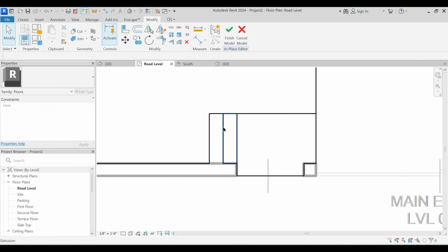1 to 2. Uh-oh, sorry. One step. Actual tread depth here, this is 10 inch. So see, only 10 inch. So 10 inch, and the flight, this is 3 feet wide. So that is okay. Run, and yeah, actual run width 3 feet. Okay, fine. With this and run right and everything perfect. Now just snap.